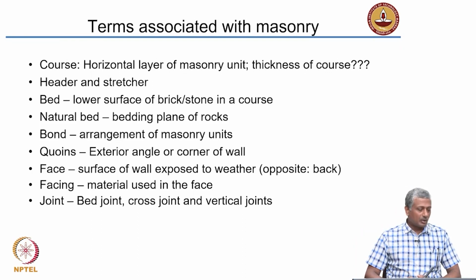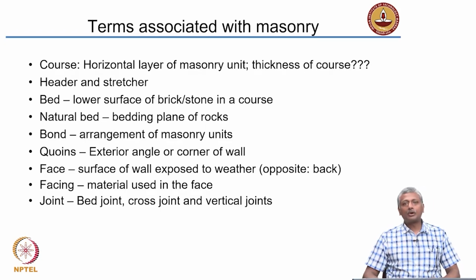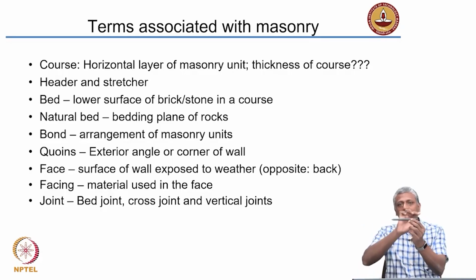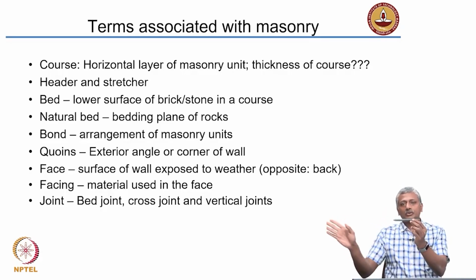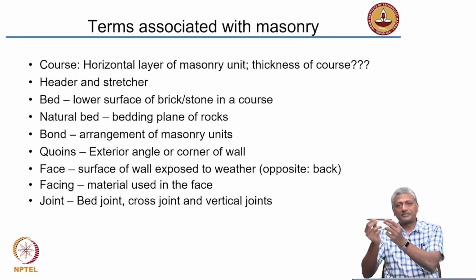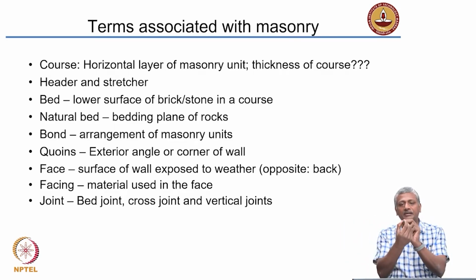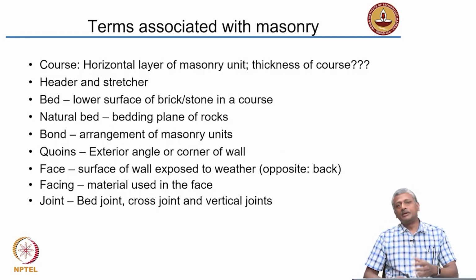Okay, now depending on how you are placing these bricks in your wall, they are called headers or stretchers. For example, if you are placing the bricks in the direction of the wall, that means the length of the brick is facing the direction of the wall, that is called a stretcher. So, it is stretching along the wall. A brick that is placed perpendicular to the direction of the wall, so the wall is running like this, the brick is placed perpendicular to it, we call it a header. Okay. So, we have to use different arrangements to satisfy the certain requirements of the bonding.